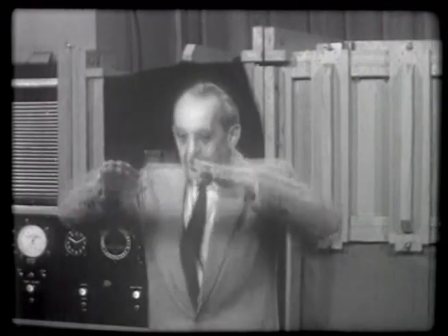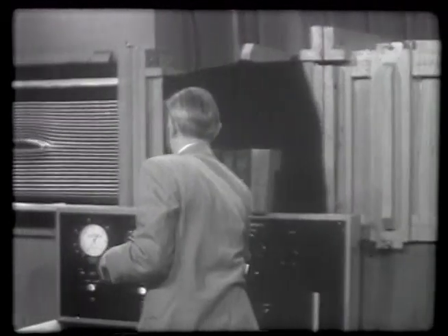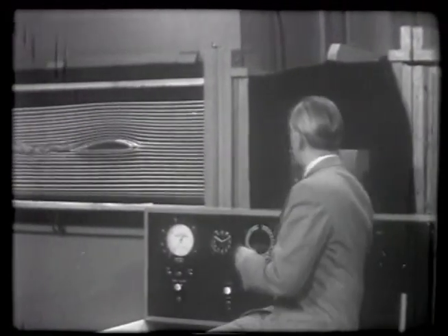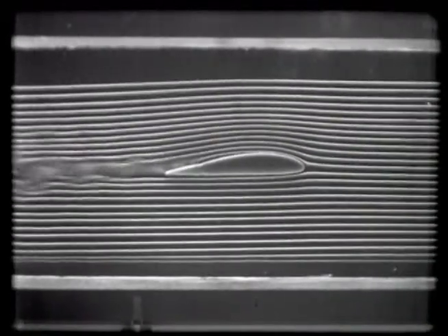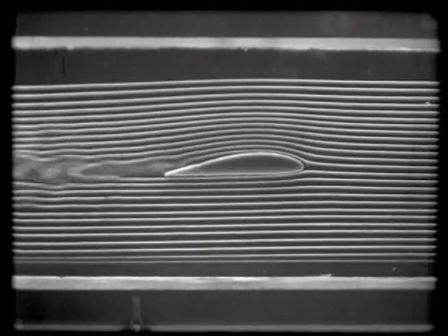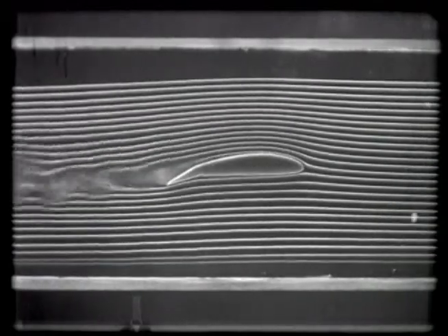How do you do it? Now you change part of the wing in angle of attack. You change only the rear part and give it a larger angle. And this is what you see here. When you make a flap back there, as we did here on this model, then you will see at once that if I change the angle of the flap, we also change the lift and have the same effect. You see it here?